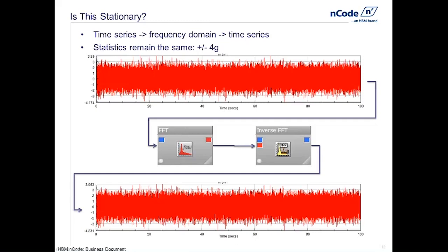You can see here, if we have data that's stationary or truly random looking in the time domain to begin with, then working into the frequency domain is reasonable, and the application of stationary assumptions in the FFT is reasonable, because if we invert that result with the inverse FFT, the time series data we get back looks a lot like the measured data we started with.